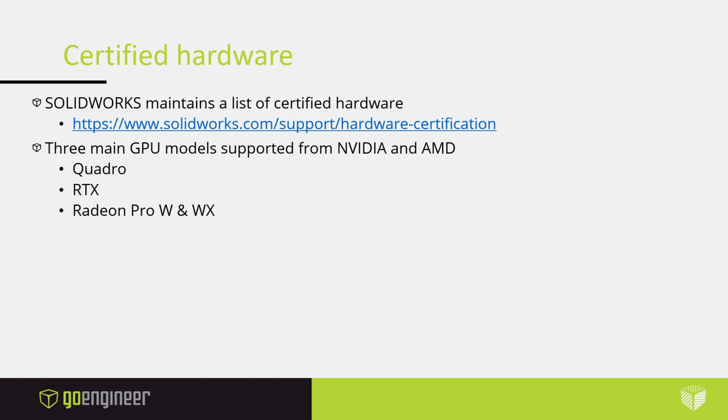Going back to the core question of this webinar, do we need an RTX A6000? I think the last time I checked, it was like $6,500. Well, if you are running super large assemblies where we're loading all those resolved, and rotating and zooming. Typically with SolidWorks, the GPU is most often utilized with rotate functions. 99% of people using SolidWorks do not need a $6,500 graphics card, but we want to make sure that the program can optimize everything and it's running a supported video card and driver.